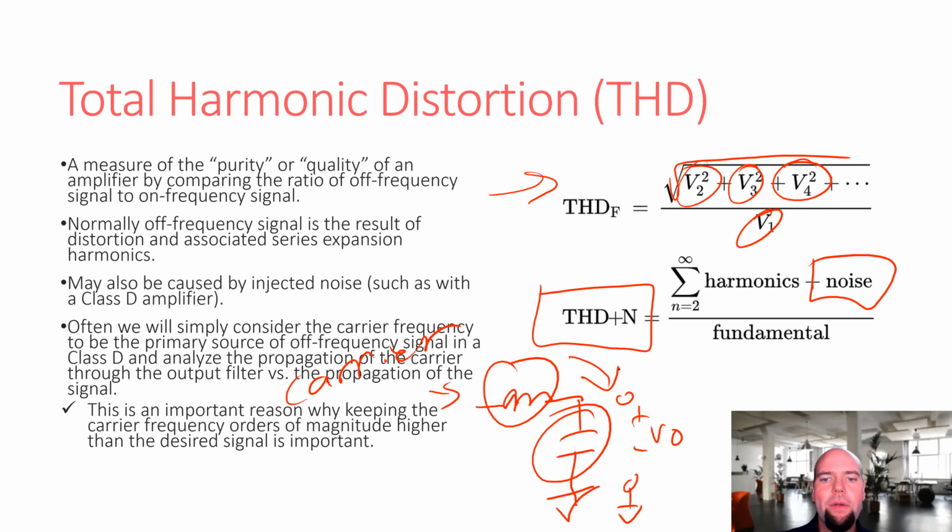So if you think of a capacitor as something that's highly resistive to low frequencies, and an inductor as something that's highly resistive to high frequencies, you can sort of see this thing as a frequency dependent voltage divider. And that's effectively what's happening. Low frequencies, the input shows up almost entirely at the output, and high frequencies, the input is heavily attenuated at the output.